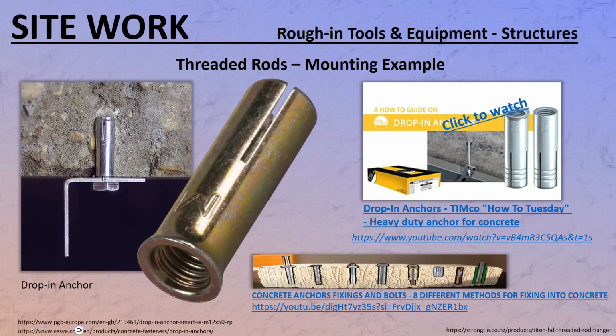Yes, you can drill that with a regular Makita or DeWalt or Milwaukee drill, but it's going to take you longer. And if you have to drill like 500 of those holes, you're going to start looking at better ways of doing it, renting or buying a heavy drill, like a Hilti gun or something like that. Then it takes a lot less time to drill those holes and they go much easier.